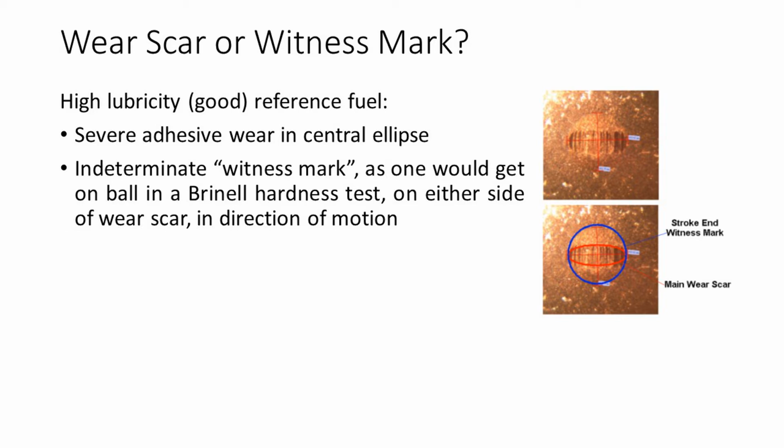This way we can determine if the measured wear area is larger than the initial Hertzian contact. Although we cannot assume that a normalized wear scar area of 1 indicates no wear, we can assume that a value of 1 indicates a well-performing lubricant compared with a lubricant that produces a value well in excess of 1 for the same test. This approach allows us to determine which lubricants perform well and which ones do not. It is a more rational approach to reporting results than simply relying on an absolute wear scar measurement. In addition to reporting a normalized wear scar measurement, there may also be some benefit in reporting the ellipticity of the wear scar.